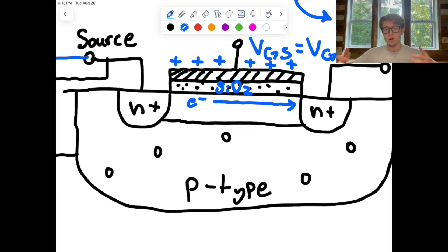Going back to our water flow analogy from Studio 7, it's just like your shower head might be the source of the water, and then you have the drain that collects all the water. Same thing. So electrons are flowing from the source to the drain, and by convention, we then say that current is flowing in the opposite direction from the drain to the source. So this is the direction of current flow that I'm drawing in orange here. And that's just a convention, okay?